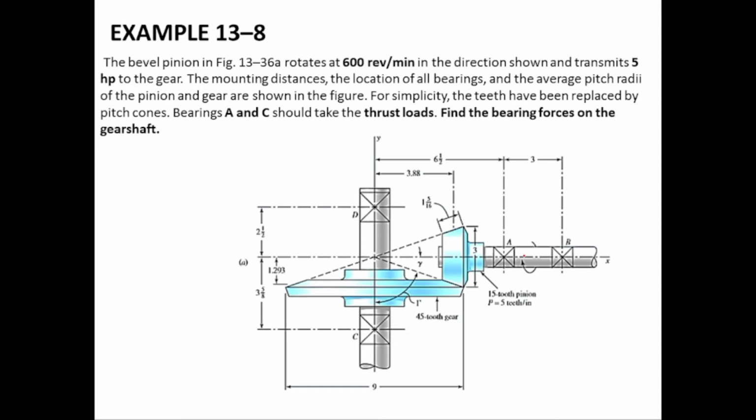Since the pinion is rotating like this, at the point G, the Wt force on the gear will be exerted such that it will be out of the page or out of the screen of the laptop or mobile, and that axis is taken to be Z. Positive Z axis is taken out of the page and negative Z axis is taken into the page.